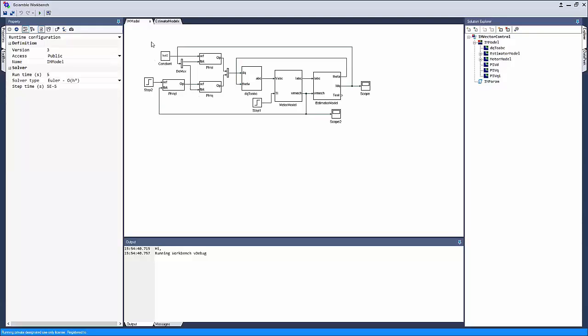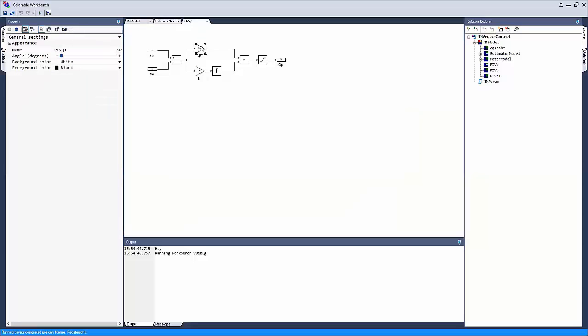And as I mentioned earlier, the stator ID current controls the flux linkage in the air gap, and the stator IQ current controls the electromagnetic torque that's generated by the motor. The loop that controls the electromagnetic torque can be further extended by an additional PI controller to do speed control. And inside this, we just have simple P and I controllers, same as what we use for a DC motor.